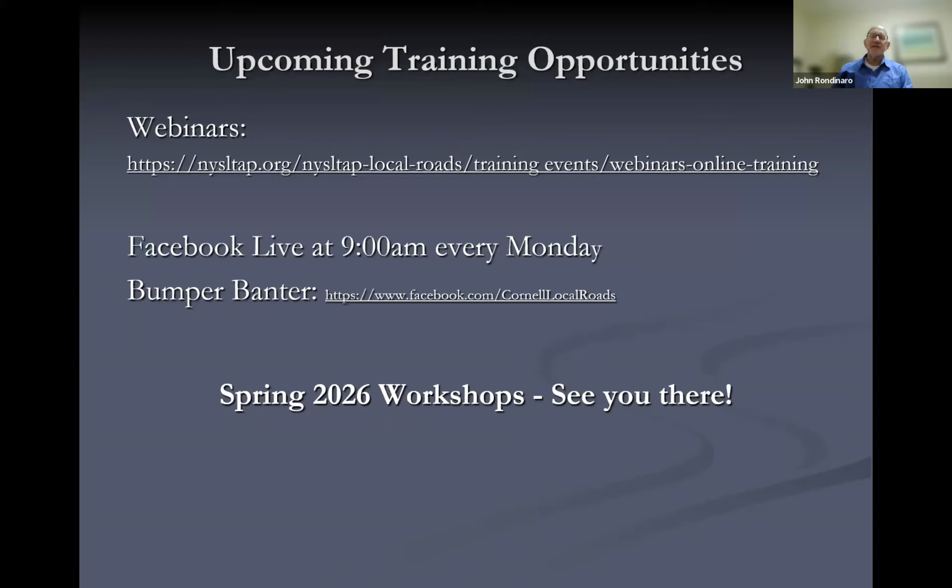Balanced mix design takes it to the next step further, because as you make something more crack resistant, it means you're really stiffening up your pavement mix or your blacktop. When you're making it rut resistant, you're stiffening it up. That is going to make it so that you're going to be inducing a higher level of cracking. And balanced mix design goes through the process to find that optimum point where you have both minimum cracking and minimum rutting.